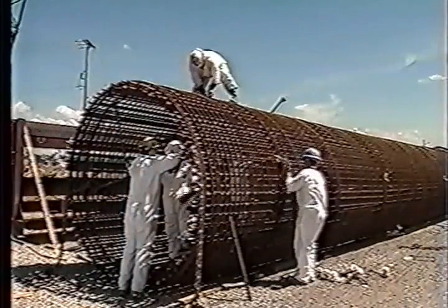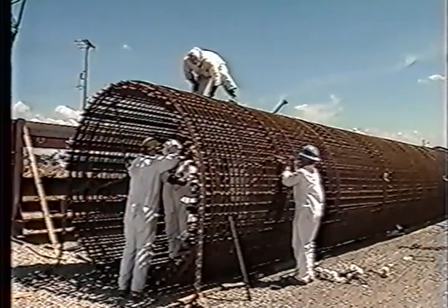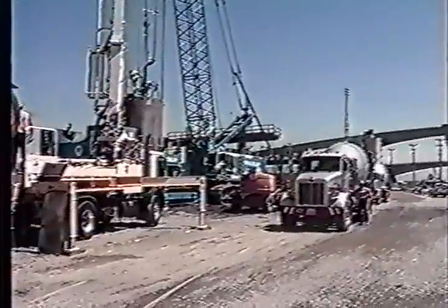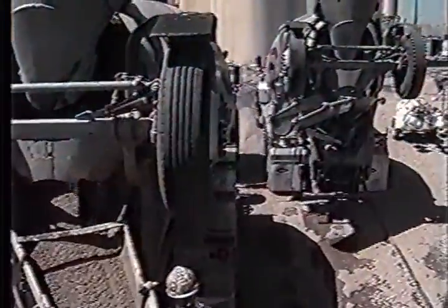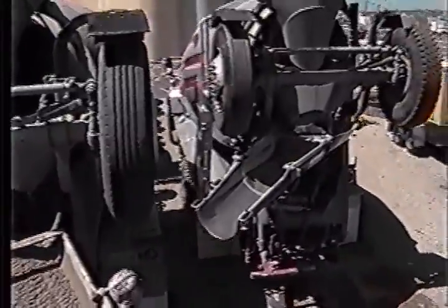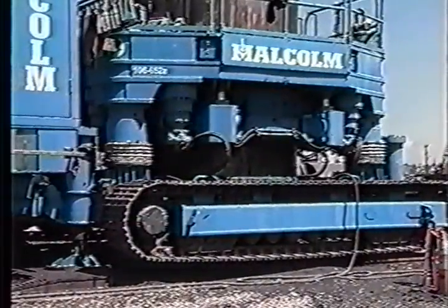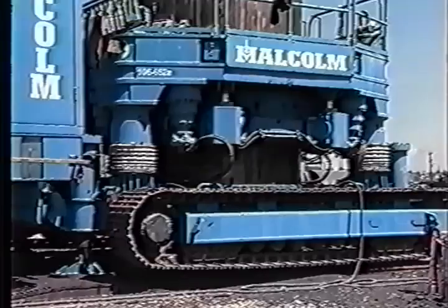The rebar cage was constructed nearby and set in the hole by the large crane. The average concrete placed per shaft was 278 cubic yards, with the largest pour at 320 cubic yards. As the concrete is poured, the rotator easily extracts each section of casing. This incredibly powerful machine has a lifting force of 1,110,000 foot-pounds.